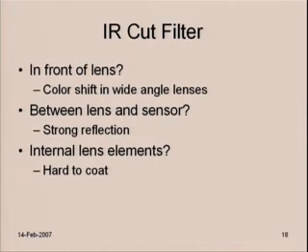And then the final thing you can do is something somewhat like what Lance was suggesting. Rather than doping the internal lens elements, you can coat them. Oftentimes you can find lens elements over which there isn't much sweep of the chief rays going through the lens relative to the surface that they're going through. Those are good surfaces to coat.